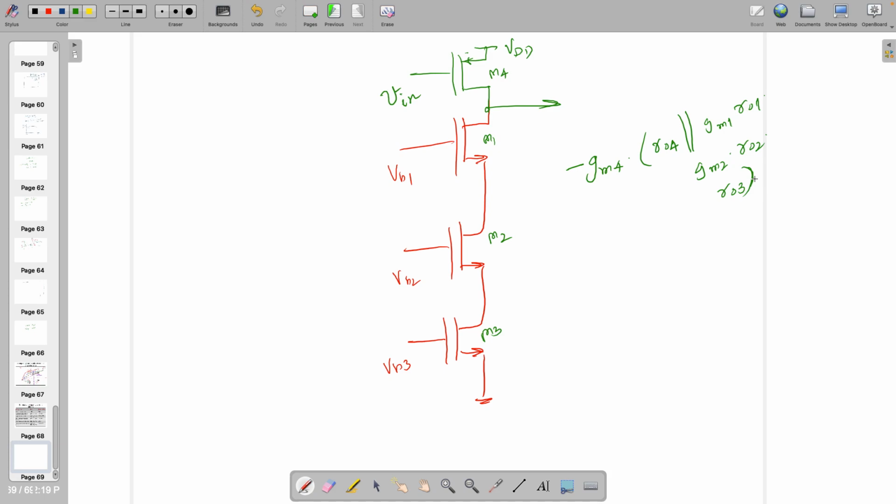Do not forget this. So if I keep it NMOS or PMOS, and if VDD is, let's assume, 0.9 volt, is it possible to tune this circuit for given values? I want to keep each one of the circuit in saturation. So is it possible? What do you think? Why?